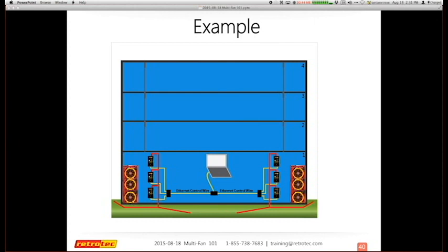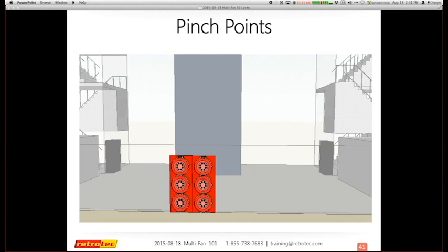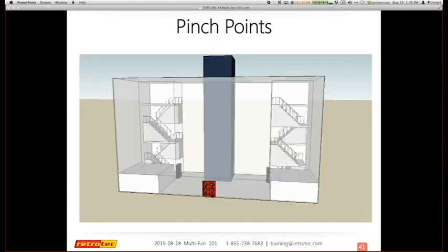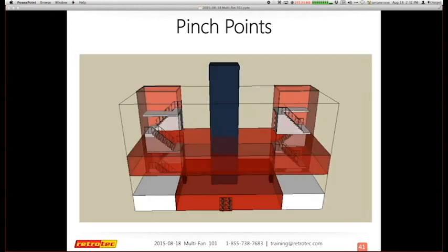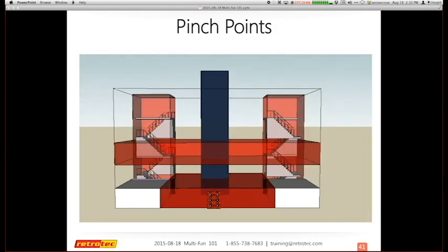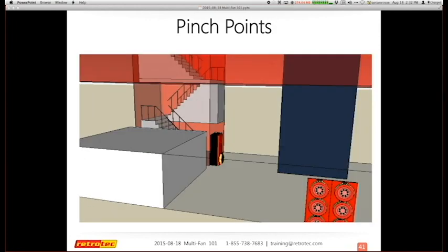All right, so now we're going to combine our exterior or reference tubes. Again, we're going to be inside the structure doing the test. This is a common scenario. Some people, again, this is a design theory in general. And the other one is now we're going to use the blue tubing, which is the input on the gauge, to actually monitor different floors. I need to make sure that I'm getting a pressure difference between the lowest floor and the highest floor, and I need to be monitoring that, as well as knowing that I am actually getting my test pressure, whether it's 50 or 75 pascals, throughout the structure. So those things have to be monitored and confirmed that you actually are in compliance.